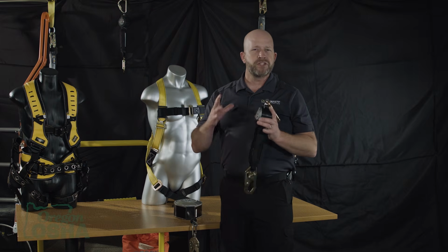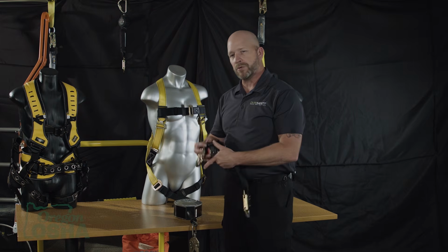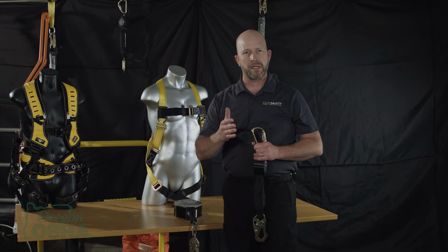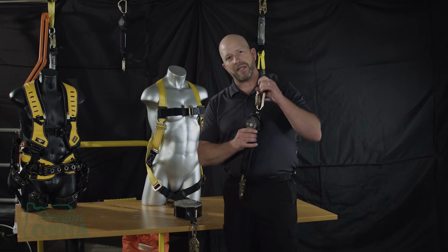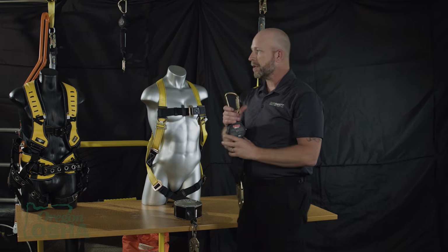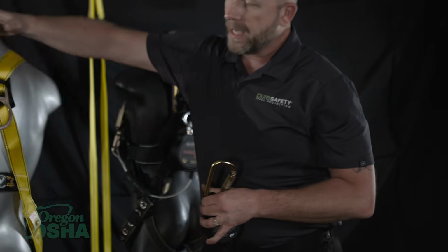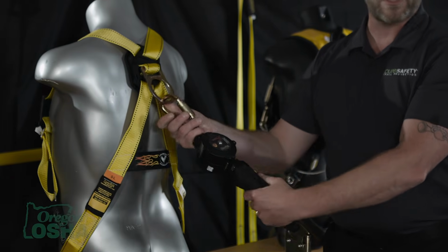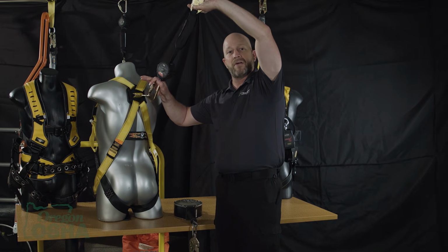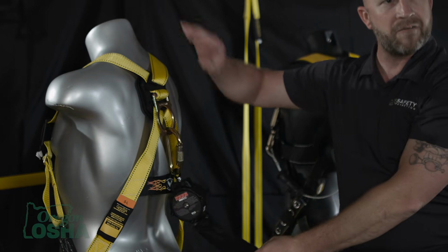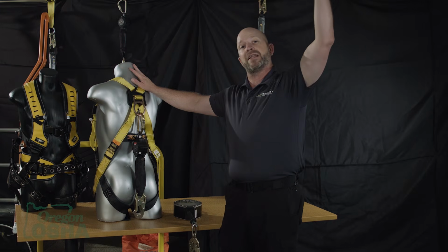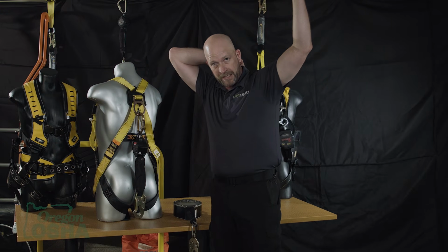Class A retractables, generally speaking, are smaller block retractables or little ones, also commonly known in the market as a PFL, or personal fall limiter. On these, we can go block to the anchor, hook to the worker, or because it's a personal fall limiter, it can be worn in a condition where the block goes to the worker and the hook goes to the anchor. It will still arrest in the same configuration, but the lightweightness of it allows it to be permanently or temporarily affixed to the worker this way, as opposed to having to find the anchor and then attach to your D-ring in that configuration.